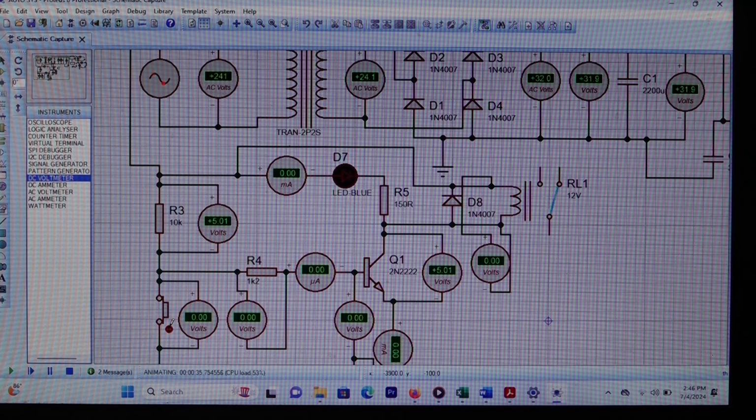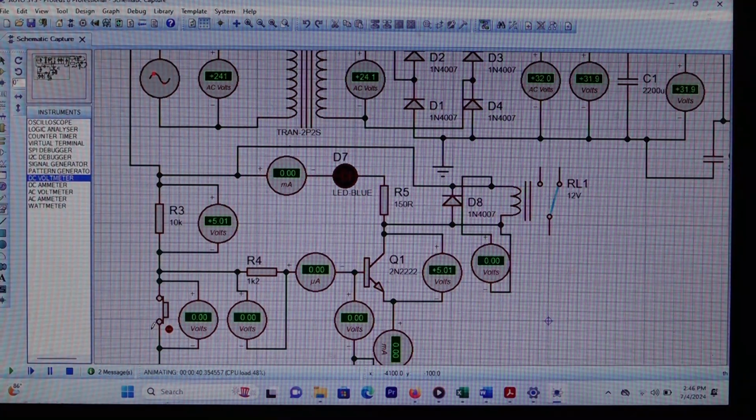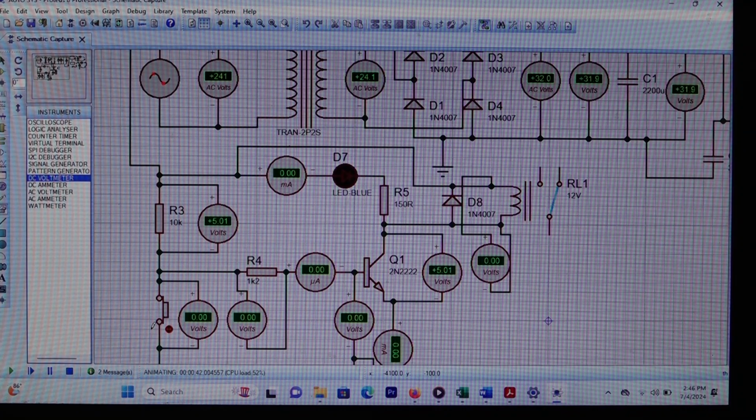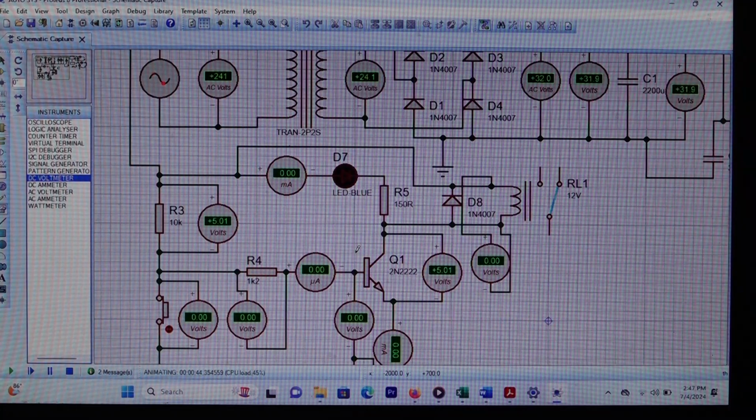From the theoretical concept that we have learned, if a relay switch receives a particular trigger voltage, then it's going to turn on the contact, right? So at this point, before we connect the loads, we can check whether our relay switch is working. When the push button is pressed, our transistor is operating in cut-off region, where collector current is 0. And if the collector current is 0, then there's no triggering of the relay switch.